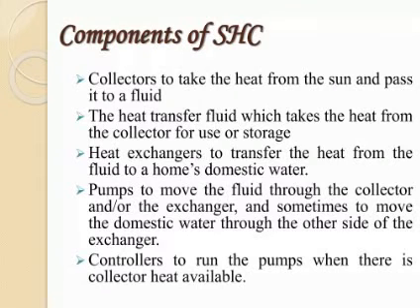The components of SHC: collectors to take the heat from the sun and pass it to a fluid. The heat transfer fluid which takes the heat from the collector for use or storage. Heat exchangers to transfer the heat from the fluid to a home's domestic water. Pumps to move the fluid through the collector and/or the exchanger, and sometimes to move the domestic water through the other side of the exchanger. Controllers to run the pumps when there is collector heat available.